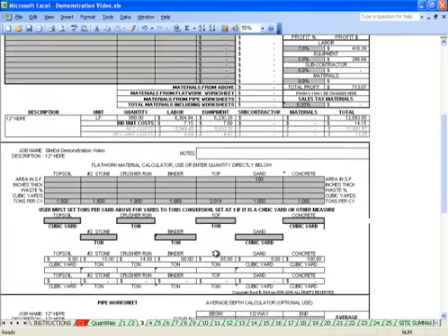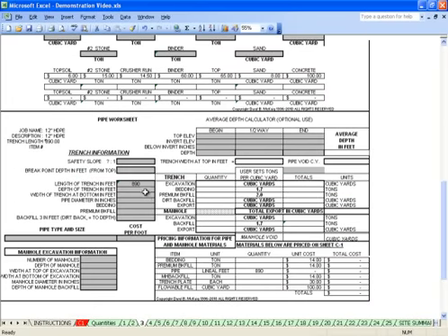Now I look down here at my worksheet, and I have a pipe worksheet. The depth of my trench is 5 feet. The width is 2.5 feet. My pipe diameter is 12 inches. I've got bedding 6 inches under and a foot above, which is 2.5 feet. And I'm going to put dirt for 2.5 feet back.